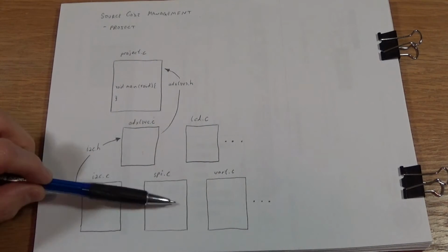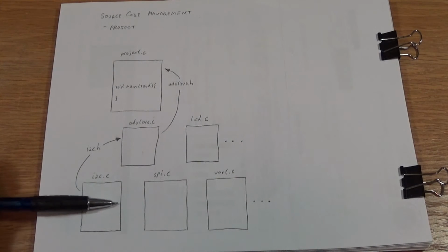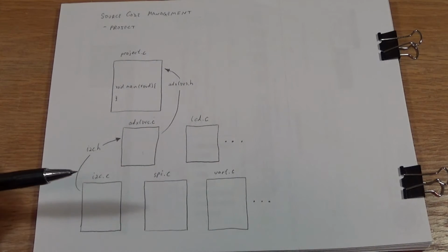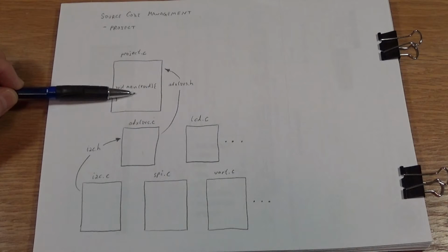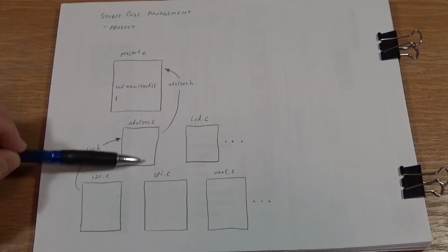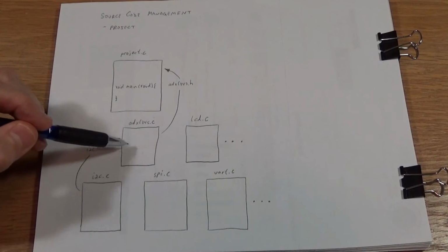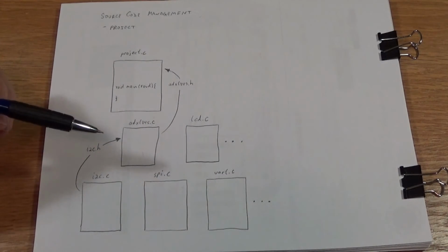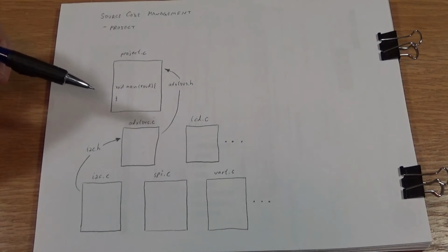And the reason why I suggest that you do these separate little files like this is that once you've got them cleaned up and debugged, you don't have to worry about them again. And you don't have to do any cutting and pasting. And also it keeps this file here, where your main work is being done, smaller, because you don't have to include all of the code from in here, and all the code in here as well. The compiler will take care of it, and then you'll have to tell the IDE, Atmel Studio, that you want to include this file and this one and this one and this one, so it knows to compile these separate files. And I'll show you how to do that when we get into Atmel Studio.